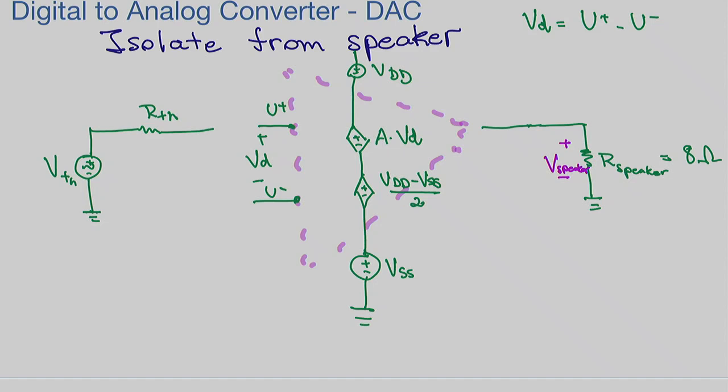What other options would there be? 0 and 3.3. But then you're only using what the DAC would give you, right? Since we have an op-amp there and we know that we can go from 0 to 10.